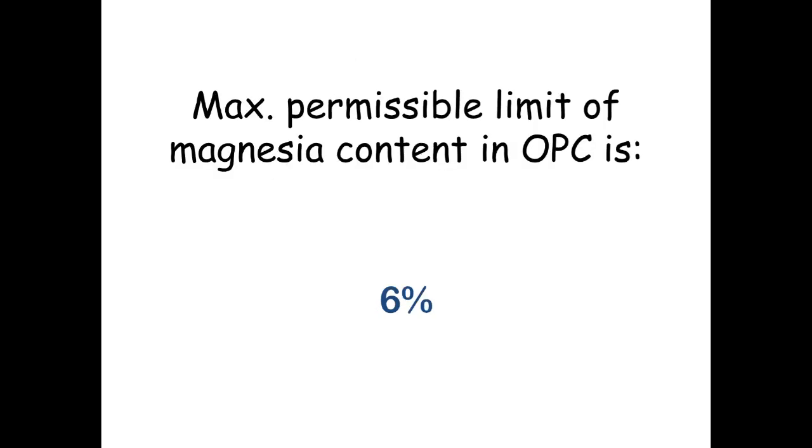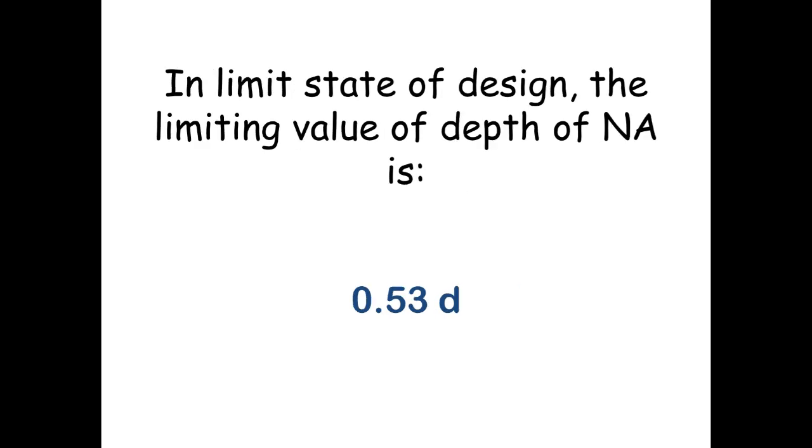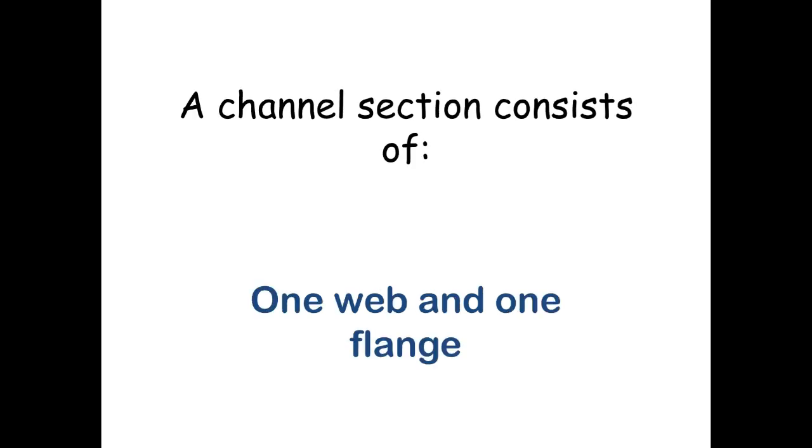Maximum permissible limit of magnesia content in OPC is 6%. The test most suitable for concrete of very low workability is VB test. In limit state of design, the limiting value of depth of neutral axis is 0.53 d.